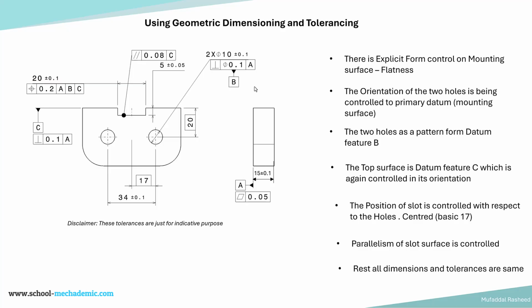Then if we look at the secondary datum, the secondary datum has been applied to the pattern of two holes, which have a size of 10 plus or minus 0.1, and they are being controlled in their perpendicularity with respect to datum A.